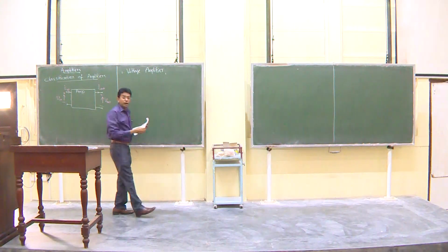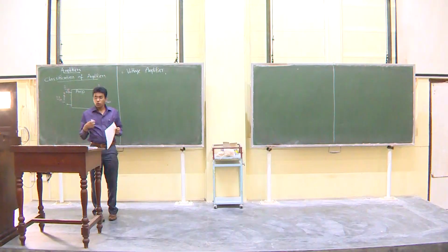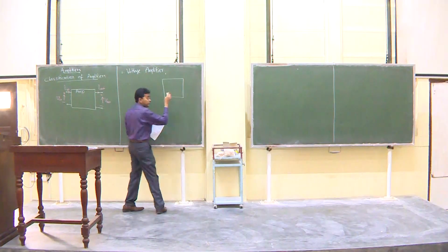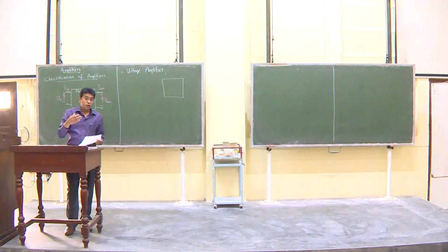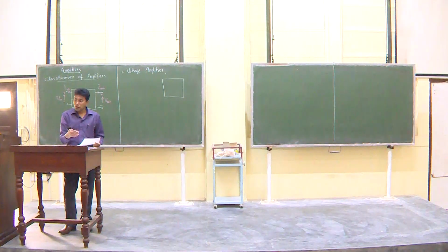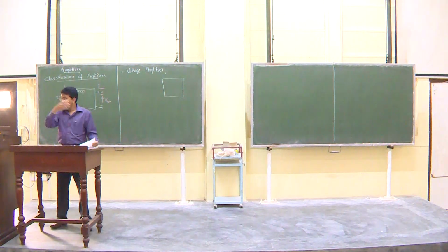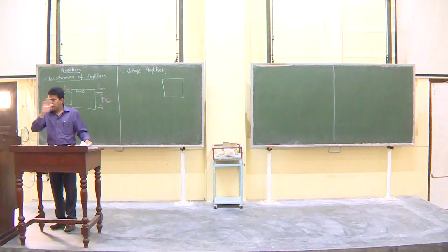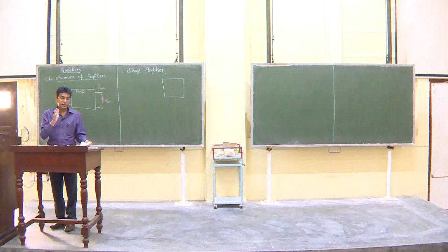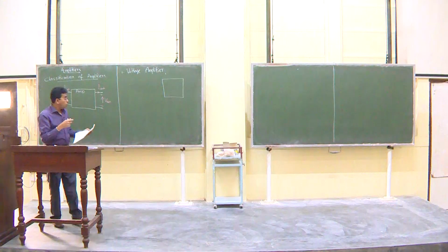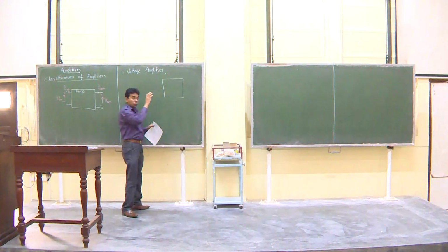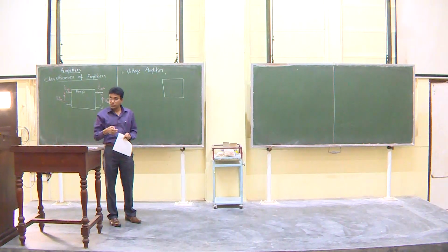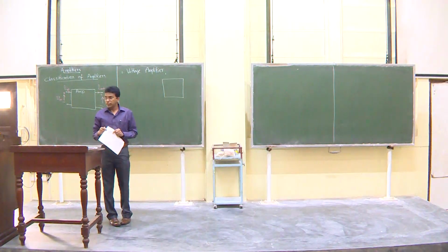In a voltage amplifier, my input is a voltage, and the output is also a voltage. If I draw the black box model, this can be implemented using op amps, BJTs, FETs, or a combination of all of these. We don't care what's inside, as long as it's a linear amplifier. Whatever is inside, we know that it amplifies the signal. In this case, it increases the voltage by a certain constant value.